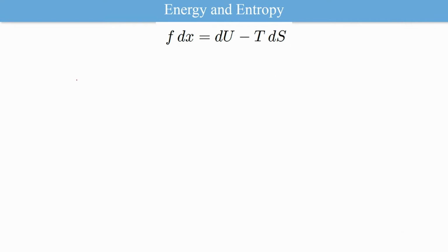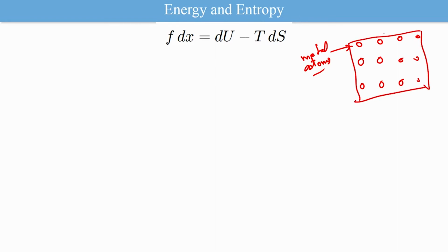Now, let us come here. So, the internal structure of a metal might be like this. Say there is a metal lattice like this, where these are metal atoms. Now, this is a very microscopic view. So, if this was a metal block and you were applying force like this, what actually happens is these atoms which are in ionic interaction with the other atoms here undergo deformation.